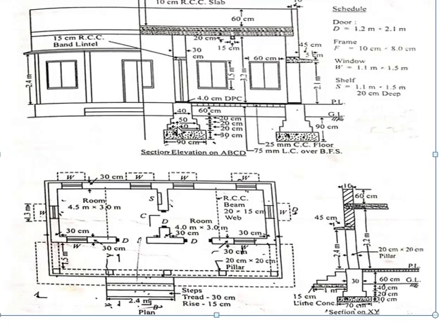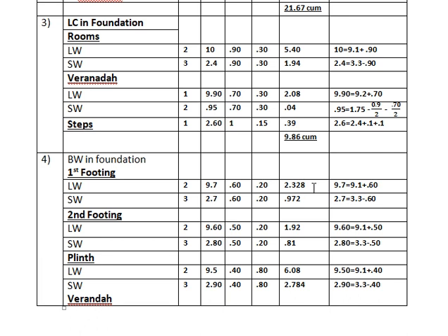the brickwork, we have the first footing, the width is 0.60. That means for the long wall we have to add 0.60, and for short wall we have to subtract the 0.60. Similarly for the second footing, in case of the long wall we have to add 0.50 and subtract 0.50 for the short wall. For plinth we have to add 0.40 for long wall and subtract this 0.40 for short wall. Here the section is same, so we simply add and subtract these things.